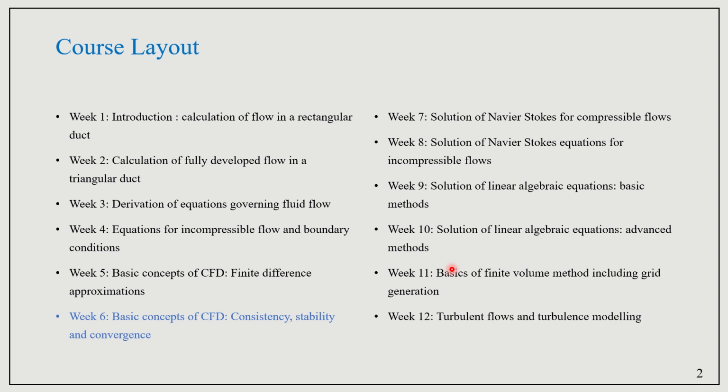We solve those four equations to get the velocity and pressure fields. But if any additional things are happening inside the system, for example heat generation or heat removal, or any reaction, we solve additional equations for energy balance and mass conservation equations for the species involved in the chemical reactions as well. All those things we have seen in the past weeks.